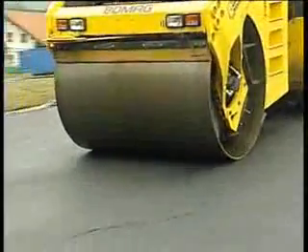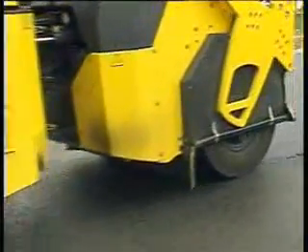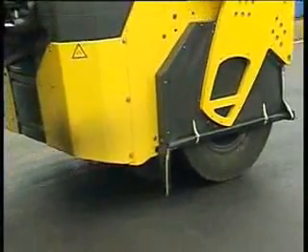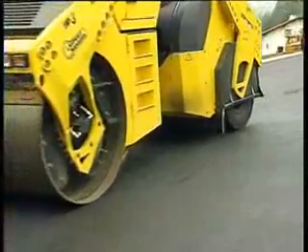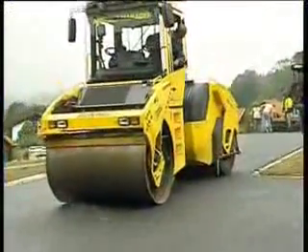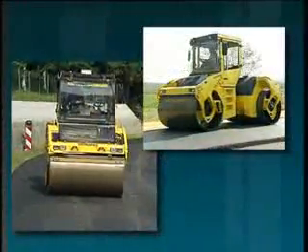Using combination rollers, contractors can achieve highly uniform compaction and good surface sealing. With sensitive mix designs, the Asphalt Manager automatically sets the compaction forces in the direction of travel. The mix is drawn under the drum rather than being pushed ahead as a bow wave.